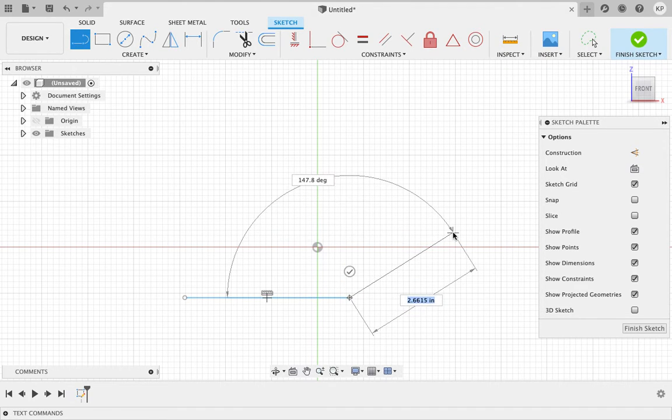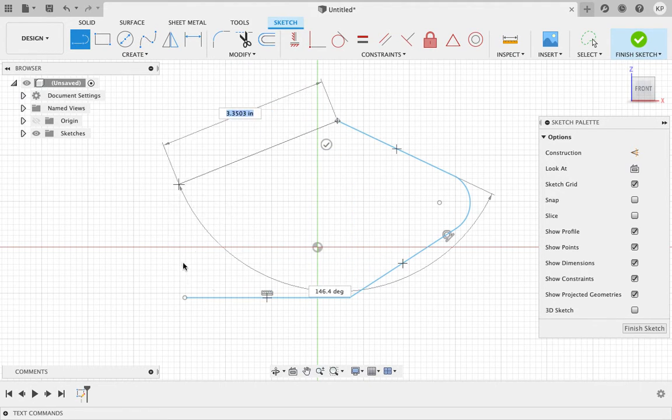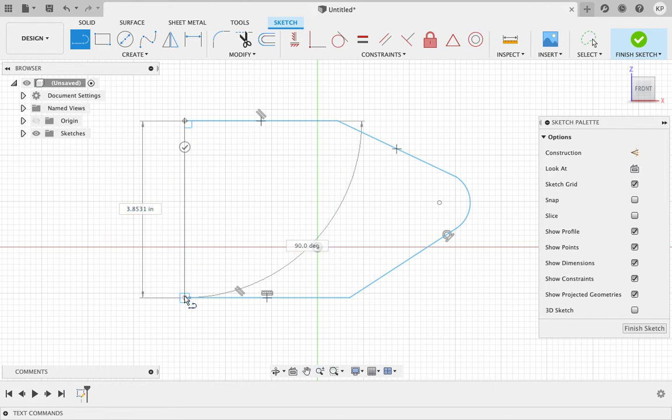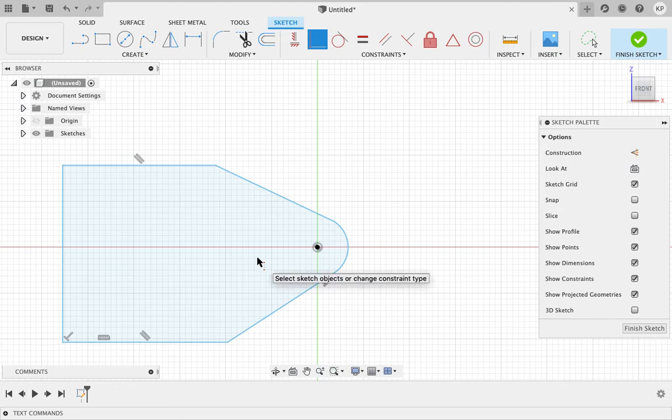Again, sizes don't matter. Up at an angle, click and hold to create your arc. Off at an angle again. And honestly, the only thing that we really want to try is making sure that that back edge is lined up. Once you have the generic shape, we're going to use our coincident constraint. Take the center of that circle, put it on the center origin point.